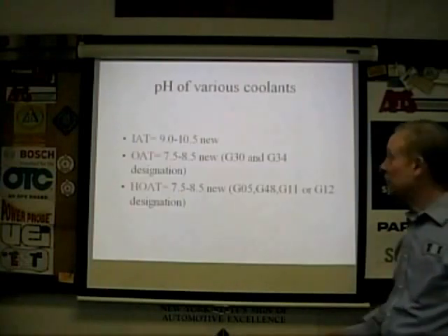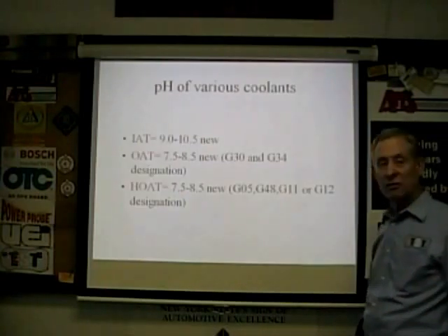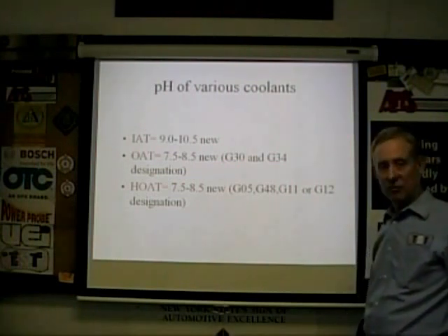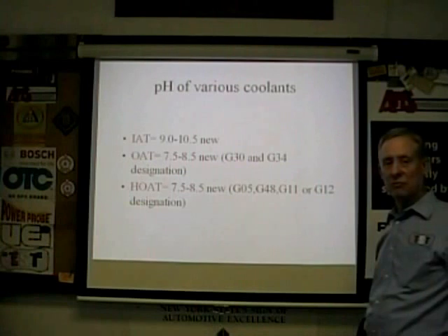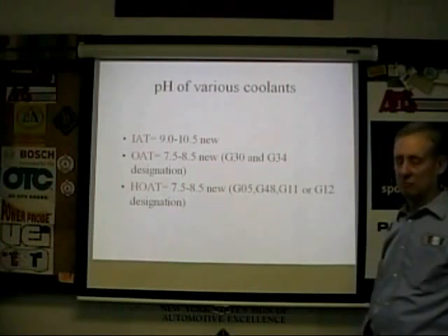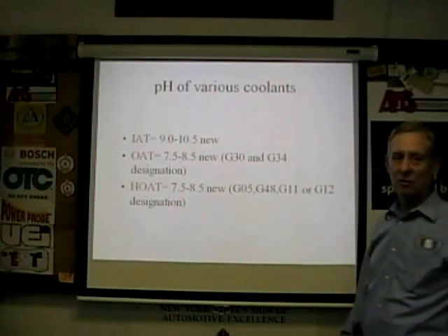So I guess really here, kind of just wrapping that up, try to use the OE or good equivalent part. Try to use the correct antifreeze or coolant, however you want to say it, meeting the spec, and use the strips to see if they're good. That's right.